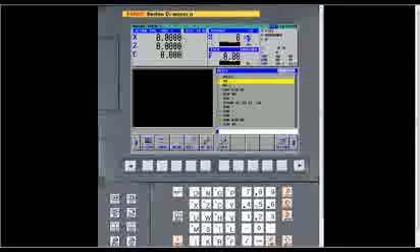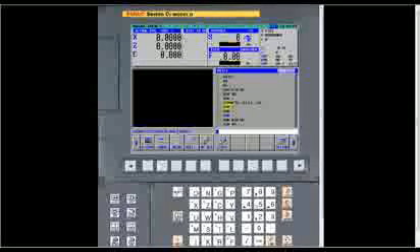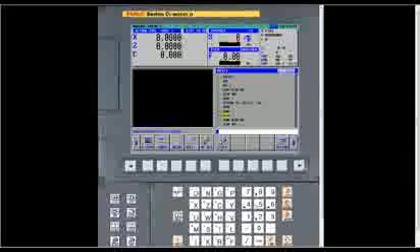And then one quick thing I want to go over right while I'm in this program. As you can see, I got a cursor over each particular spot in the program. And see, when I put it over the M5, down here at the bottom it says M5, spindle stop. I cursor down to G30, it comes up and says, okay, G30 is a second, third, or fourth reference position return. M30, it knows it's the end of program. G1900, that's cylinder blank figure. That's part of the learning tool that we talked about earlier also. As you page down through the program, it'll tell you what everything is. G90, G40, gives an explanation of that.